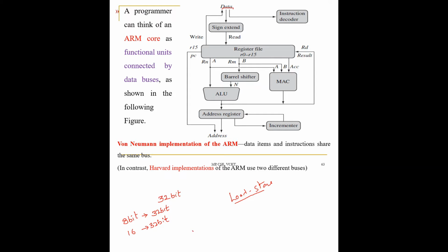So it means that you have a processor here and there are registers inside the processor. We'll look into these registers later. And there will be memory in which you will be loading the data or the instructions. The data that has been loaded in the memory, if it has to be processed, will be loaded to the registers present in the processor, and in order to move the data from the memory to the registers, we'll be using the load instructions.